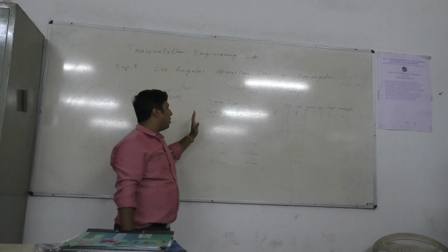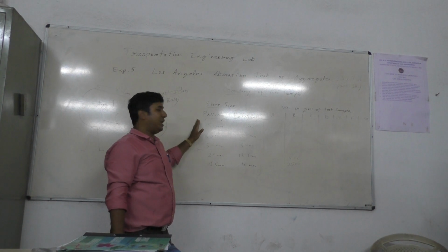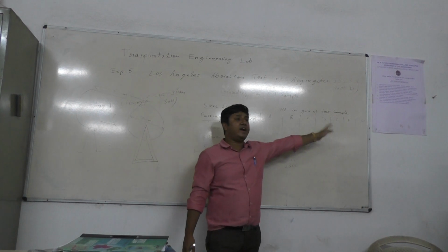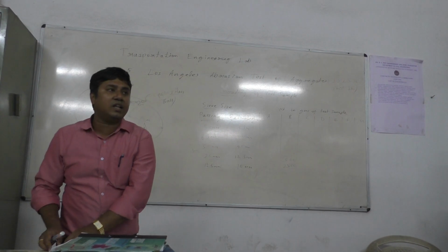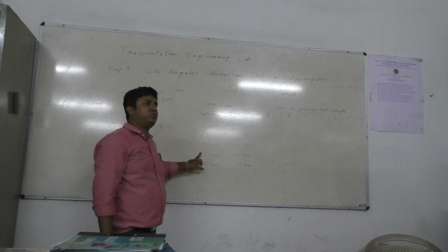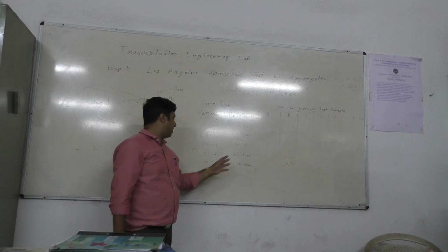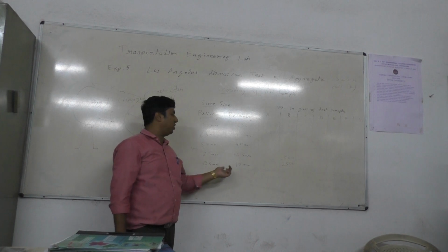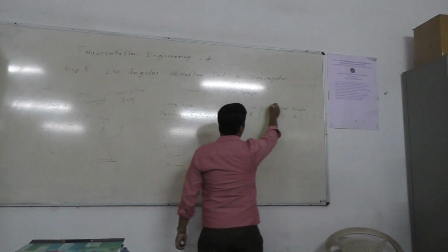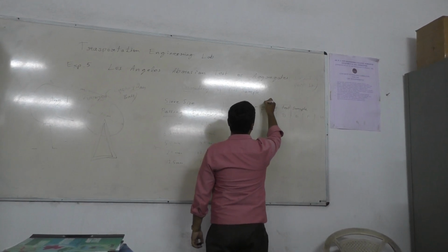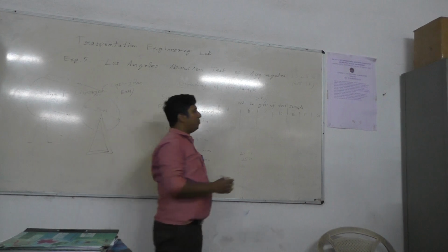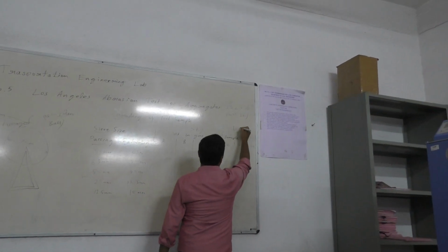It starts from 80 mm, when it is passing 80 mm and retained on 63, then 63 and 50 and so on. Based on this, we have the graded classification. Here in our test we will take the range of 20 mm, the aggregates passing 20 mm and retained on 12.5, and another range passing 12.5 and retained on 10. We will take a quantity of around 5 kg. From A, B, C, D up to this range, the weight of sample to be taken is 5 kg, and beyond D, that is here G, we have to carry a sample of 10 kg.